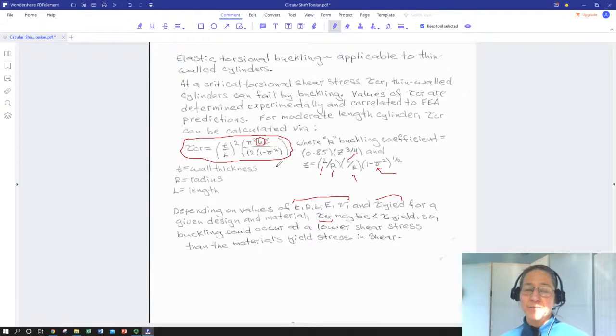So even if you don't want to go through the full calculations, you can imagine how things like polar moments of inertia and average radii might change for a different shape, and at least get an idea of what if I went away from a circular cross section, what effect would that have on my design. You can think through that using the same types of relationships that we've used to derive our circular case. So, hope you have fun designing torsional shafts.